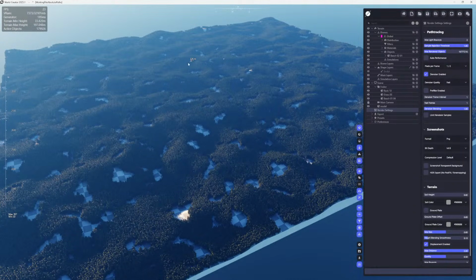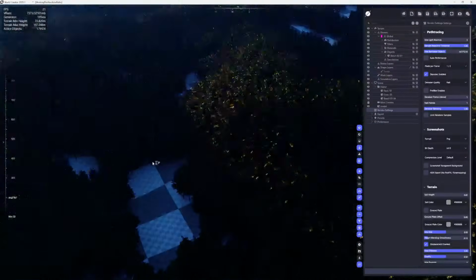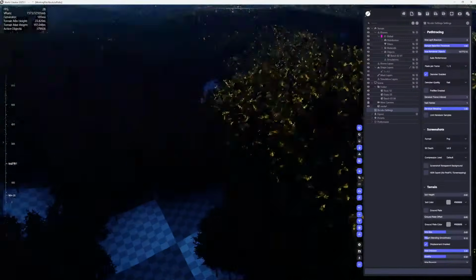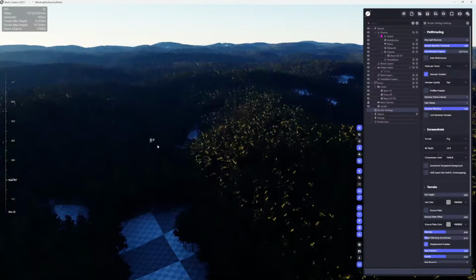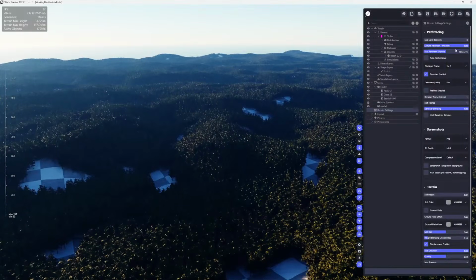Another one, if the lighting is too dark, like if you move in like this, there are currently two reasons. The main reason is that we don't have translucency yet supported for the object. For example, the leaves typically let light rays pass through. So there's a light ray that goes through the leaves and still hits something on the ground and can bounce around. In this case, it just hits the leaf and goes back to the space or wherever it came from. So it never reaches specific light. That's why it's too dark here. You can control this a little bit, but this is just a temporary solution until we get the translucency and the hardware ray tracer included.